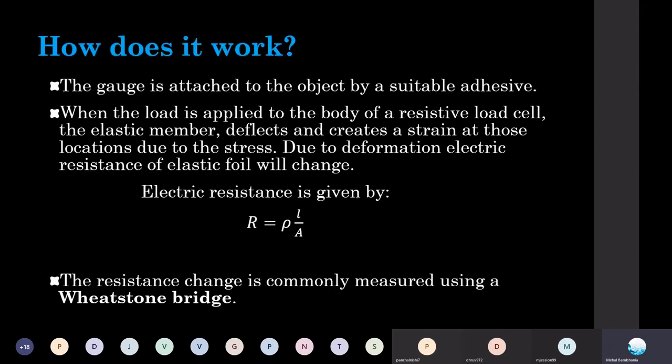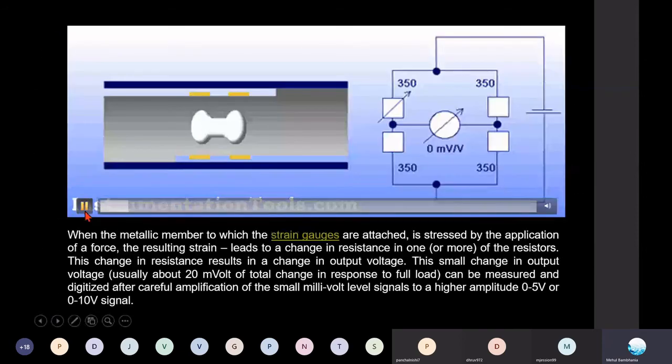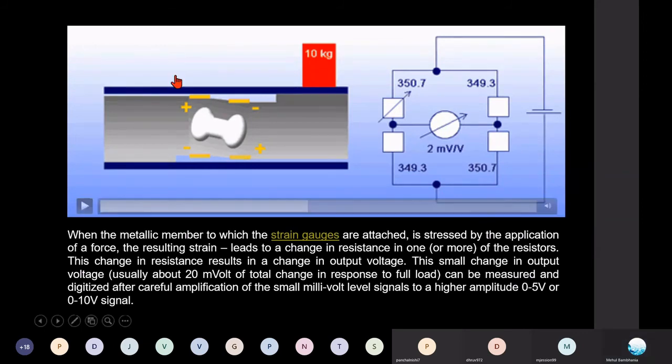So ultimately we reach what amount of force is acting on this element. This is how the reverse calculation is done by means of certain sensors. We will not do that calculation ourselves, but this entire load cell is made such that it performs the reverse calculation and reaches from the output, like let's say from 2 millivolts of output, to what amount of force or load is acting on this strain gauge.